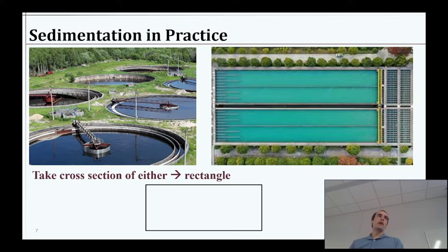And it turns out both work very similarly in that you have water flowing across and particles sedimenting down during the time. And you could even take one of these circular ones, which are essentially pouring water out from the middle, and it's heading out to the sides of the chambers. It's a radial system, and it's collected around the edges.